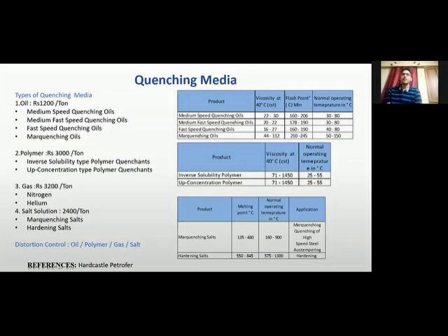In case of polymer bath cost consumption, there should be some limitation also to use polymer in furnaces. In batch furnace or continuous furnace, you cannot use the polymer because of the mixing of water or water vapor issue. But where open quenching is available, or induction heating, we can use the polymer.